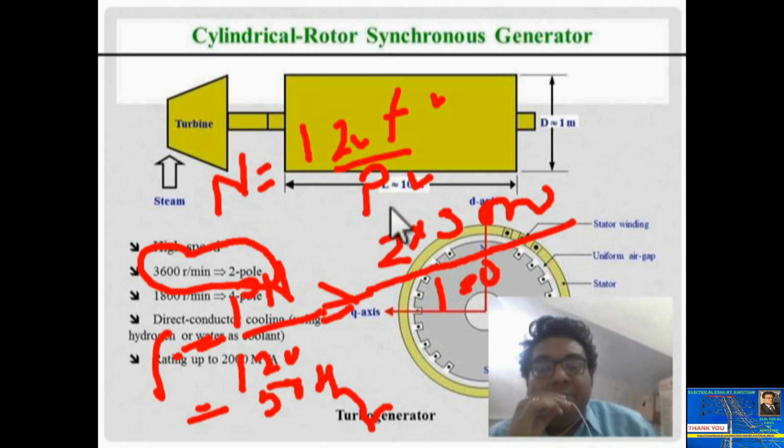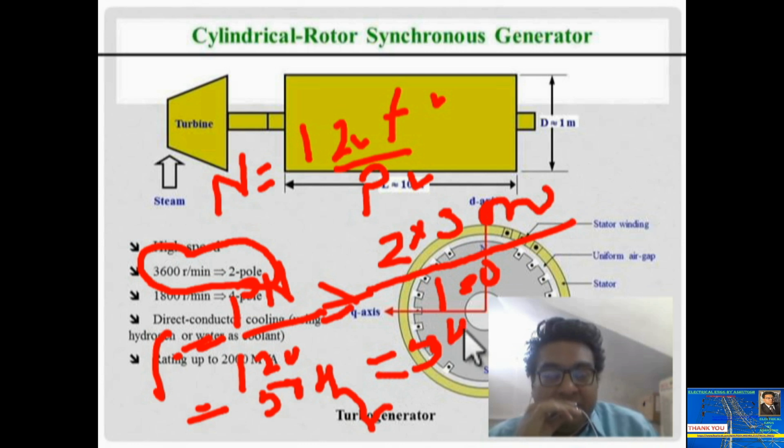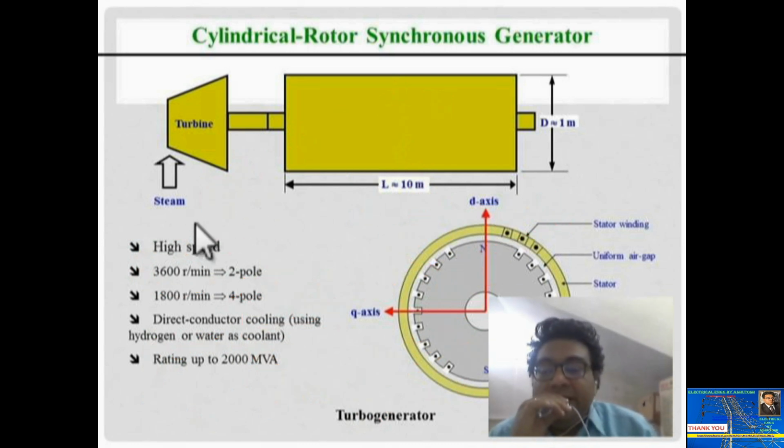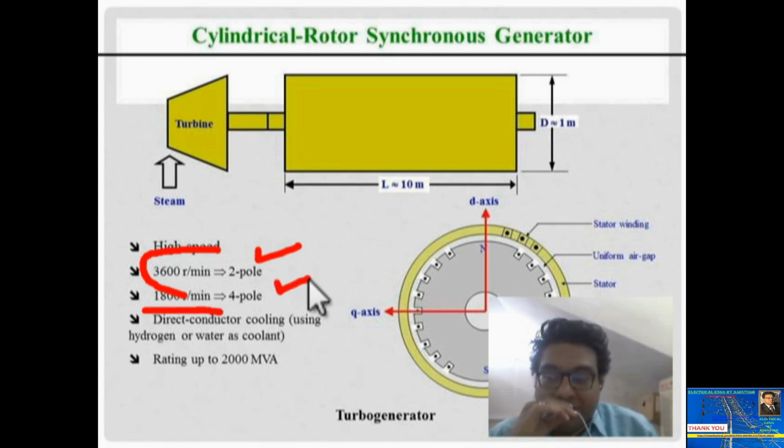And if you put 4, if you put number of poles equal to 4, you will have to select 1500 rpm, and then for 1500 multiplied by 4 divided by 120, another 50 hertz will come, so the same answer will come. So this is the combination selected in India, and as per the picture, you can see guys, here in our country 3000 rpm is taken with 2 poles and 1500 rpm is taken with 4 poles. So guys, this picture that I have taken may be according to the United States of America or another country. Okay guys, so now we will take the